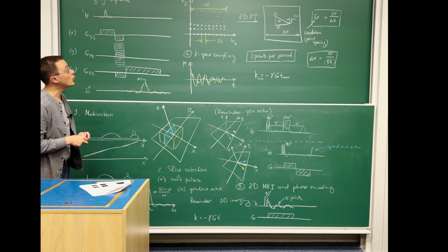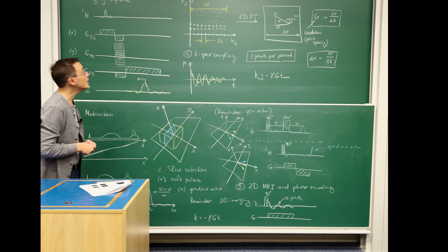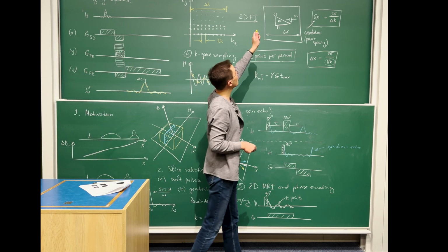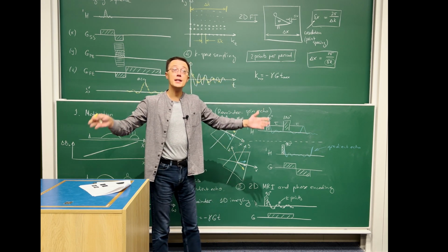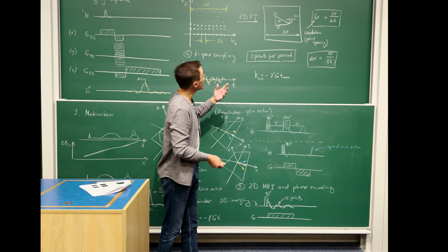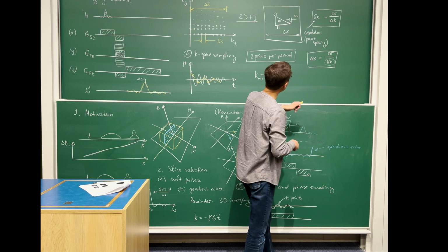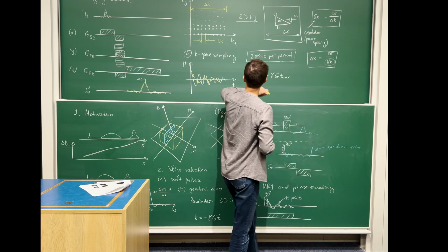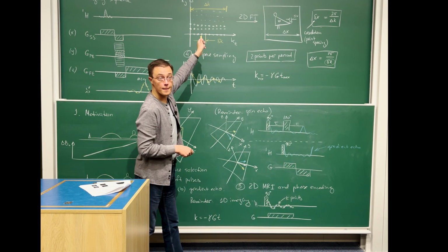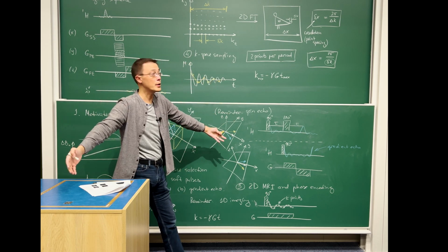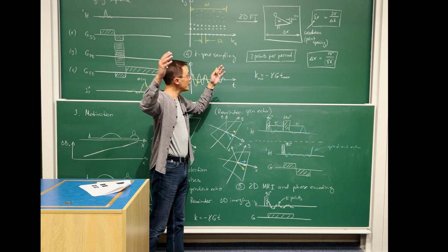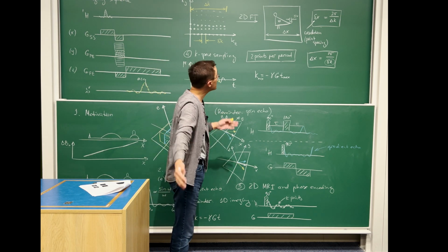Assuming we have done all our sampling correctly, the two-dimensional Fourier transform will get us the image. The two parameters of the image are size and resolution. Size is determined by the closeness of the points in the K-space. The finer the spacing, the greater the frequency we can digitize, the greater the range of locations we can reproduce, the greater the size of the image.